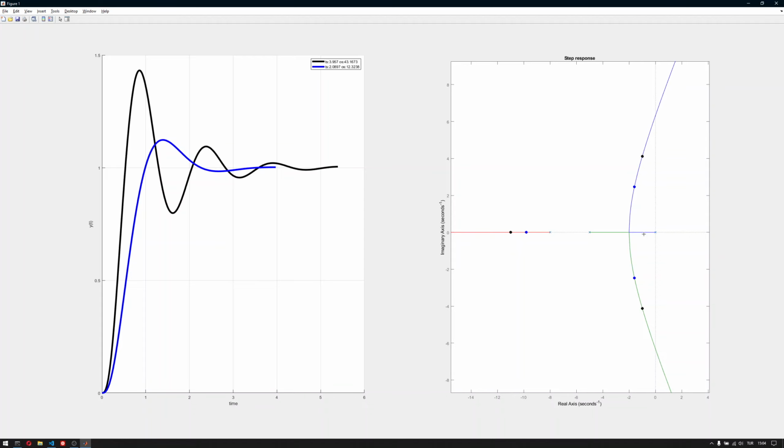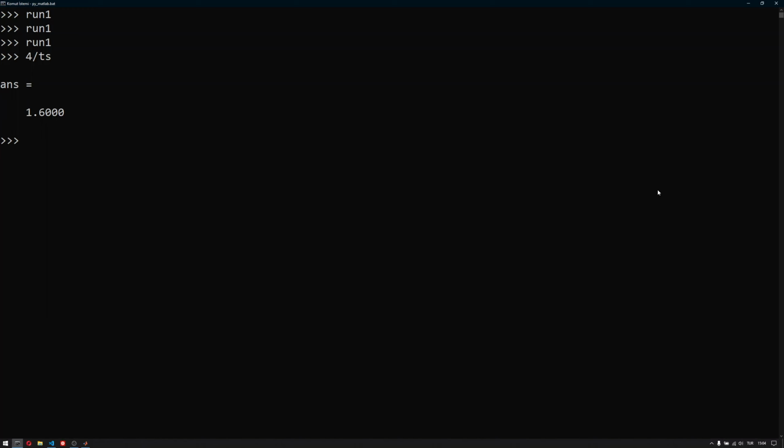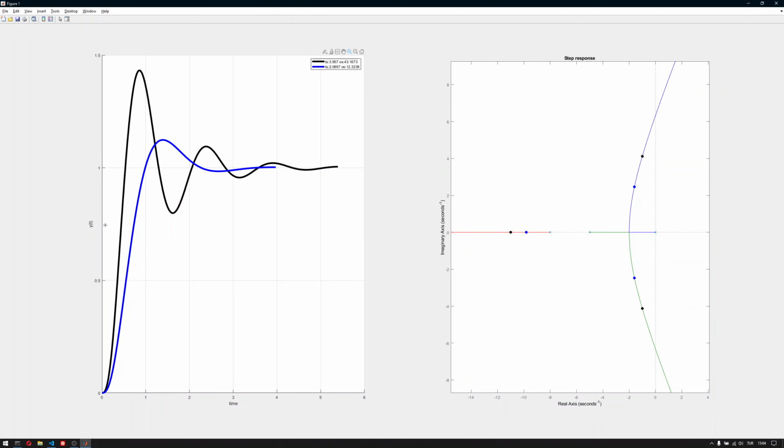And if it's more to the left, on this root locus, I can see it will have a lower gain value. So the k-val here is 84, where it was 198. So it's a lower k-value. It's earlier on the root locus, and I can see that the p-value here is also a lower value.